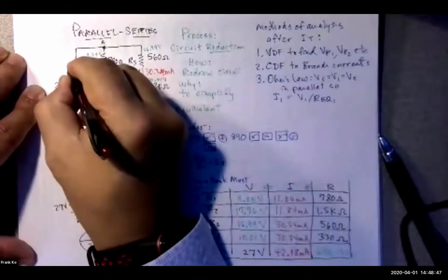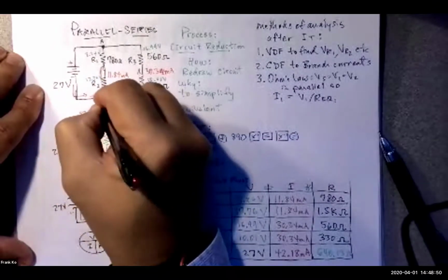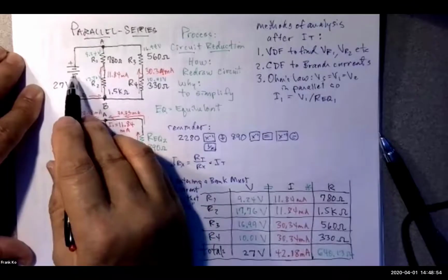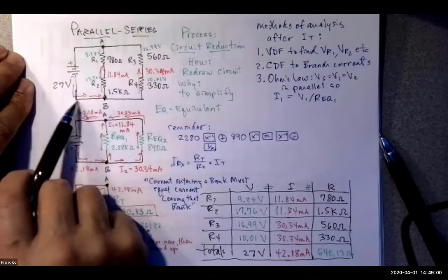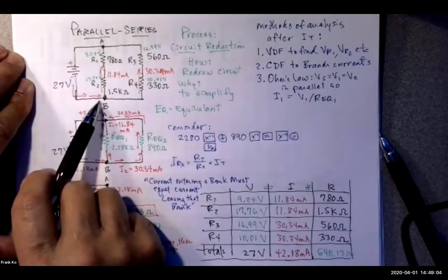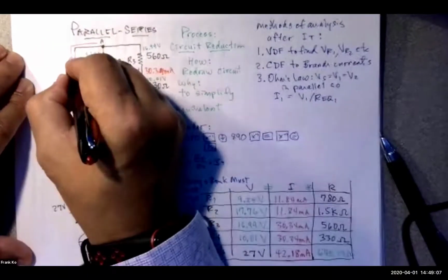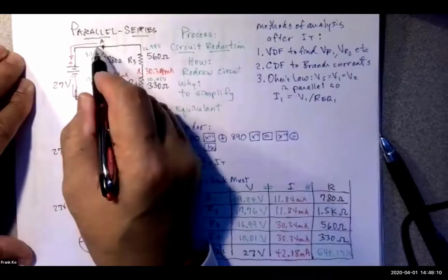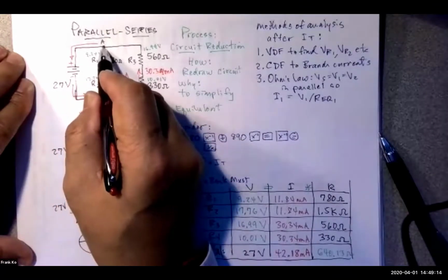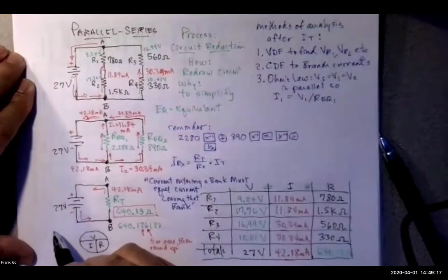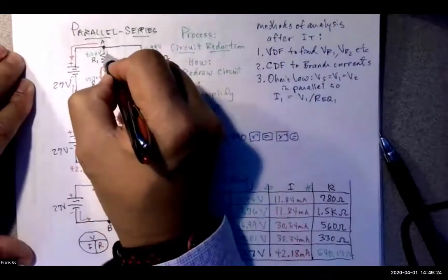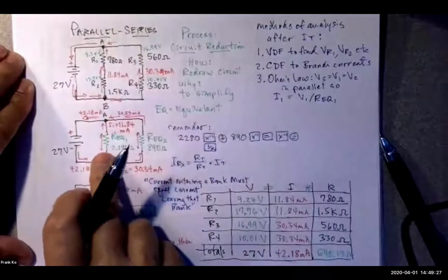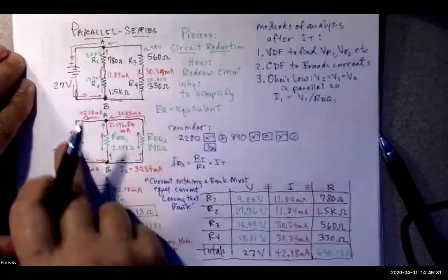The current that leaves the source comes down and it sees node B. Between the negative plate of the voltage source and node B, was there any series component in that wire whatsoever? None. Take a look at the current coming back from node A. Is there any single series element in that wire between node A and the positive plate? The answer is no. So this particular circuit does split at node B and the currents combine at node A. It is fundamentally a parallel circuit, as evidenced by the middle drawing.